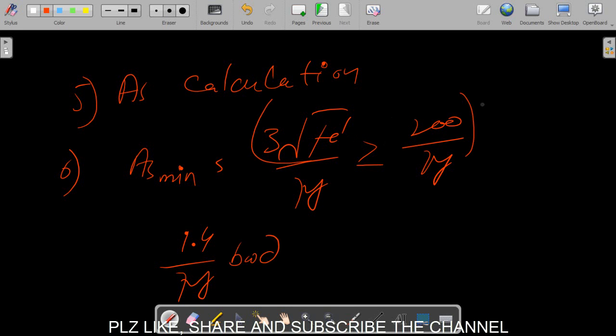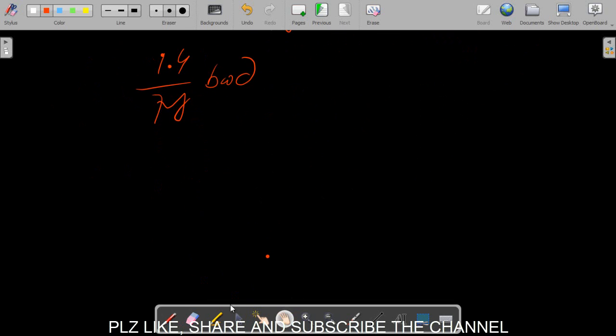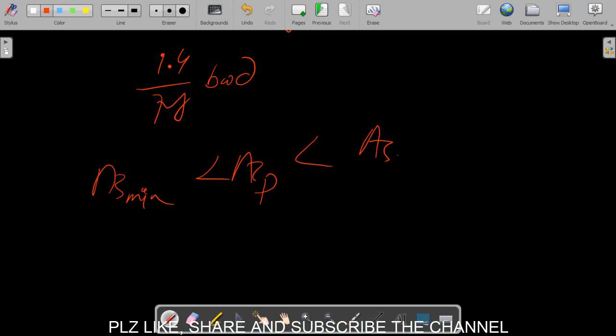This should be multiplied with bw into d. And we will check whether our area of steel provided is greater than area of steel minimum and less than area of steel max.